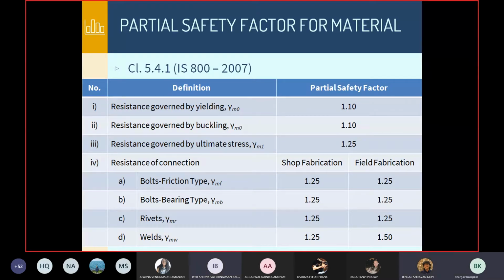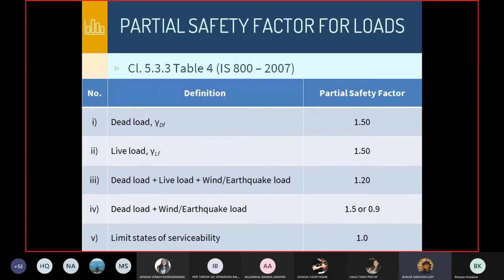Someone else also had a question. Yeah, I just wanted to ask something very similar. How are these numbers derived? This is page 21 or 20, right? The partial safety factor numbers on this one, but there was another table about the earthquake loads and the wind loads. Yes. How are these numbers derived? These numbers are derived on the basis of a lot of experience with the loads you can expect in the structure. So this is an empirical number, and it is based on engineering judgment.